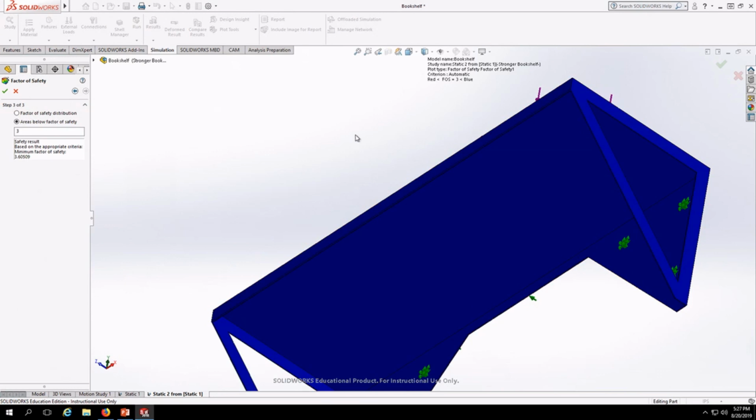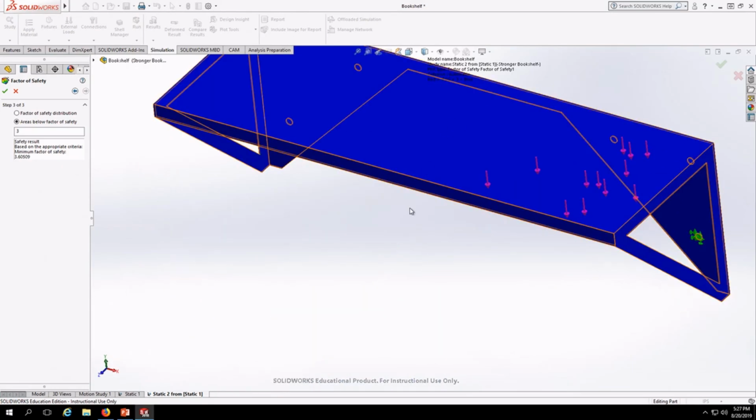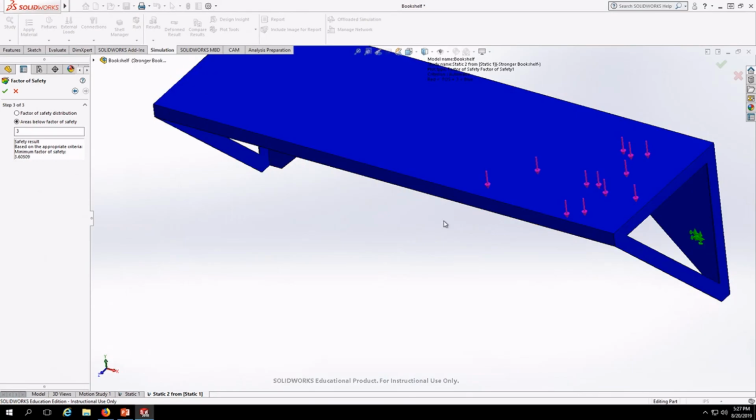Okay, so we've done some finite element analysis, but we definitely used the sledgehammer approach for this one. Oftentimes, it's best to go through the work of optimizing your input before running the simulation. This means looking for planes of symmetry, or modifying your mesh to be finer in areas of high stress. Another way to optimize is by choosing the element properties to best fit your application. Those last two go beyond the scope of this video, but symmetry sounds doable.